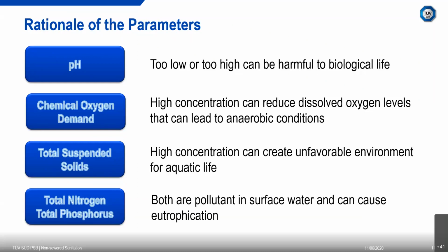If pH is too high or too low, the aquatic organisms living within it will die. pH can also affect the solubility and toxicity of chemicals and heavy metals in water. Chemical oxygen demand, or COD, is a measurement of the oxygen required to oxidize soluble and particulate organic matter in water. COD is an important water quality parameter because it provides an index to assess the effect discharged wastewater will have on the receiving environment.